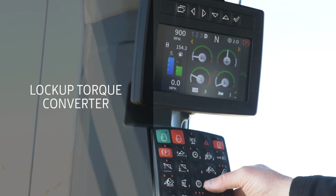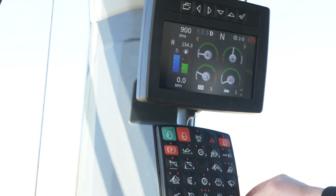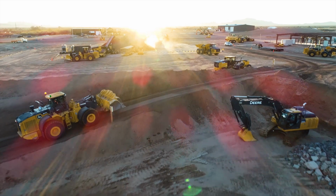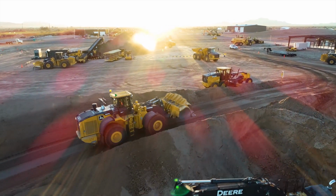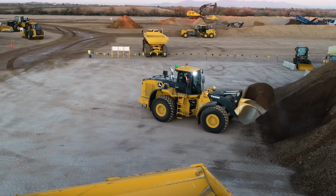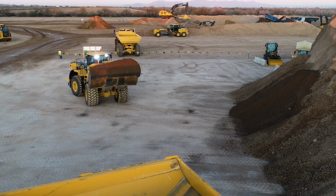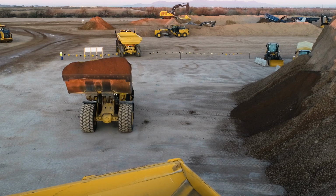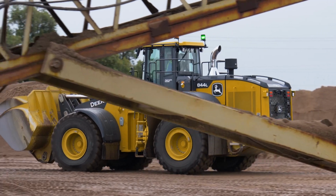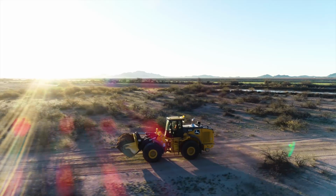When equipped, the lockup torque converter will be enabled in gears 3 through 5, regardless of the SSM setting. The switch controls the lockup torque converter in second gear only. When performing load and carry or transport operations, it is recommended to always enable this feature. For V-pattern loading operations, the lockup torque converter can be applied in second gear, which will alter machine rise-run performance. It is recommended to turn off the lockup torque converter when operating in this application. For any type of load and carry or transport operation, it is recommended to turn this feature on.